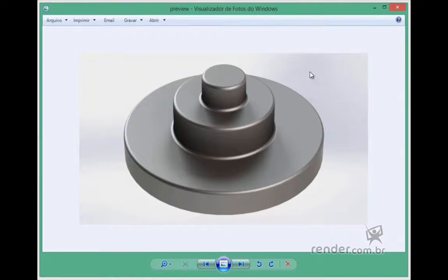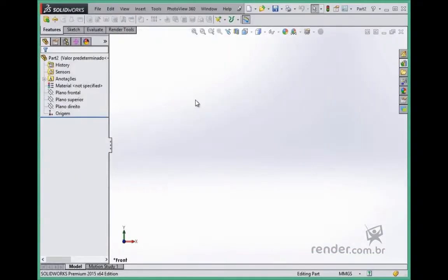Let's start by choosing the profile that contains the largest number of details, reducing the number of features needed to define the geometry. In the part file, in which we set up, we'll draw the sketch. In all of them the geometry is the same. However, for the part to be oriented correctly as in the picture, we need to choose the right plane. Choose the right plane and on the floating bar, we click on Sketch.